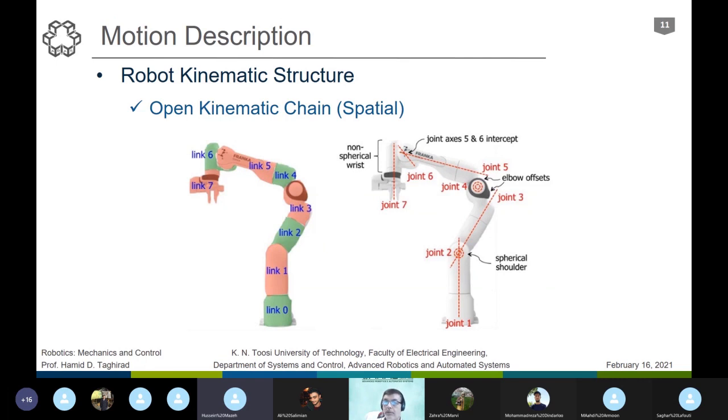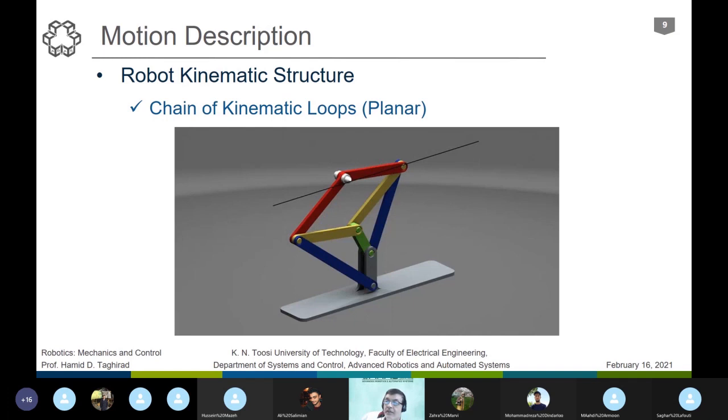The thing is, the number of actuators that you have will result in the number of degrees of freedom of the end effector. As you see here, we have only 1 degree of freedom, and we have only one translational motion here. This is a one-to-one actuator here. We are using the structure to make the system quite stiff, not to add motion to the system. The category that you see here, in terms of the motion and the actuator, usually the number of joints, we call it the joint space.